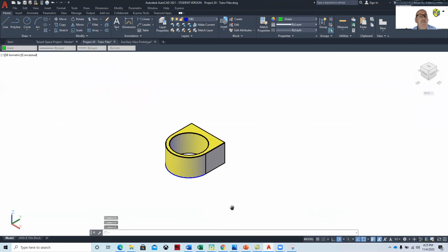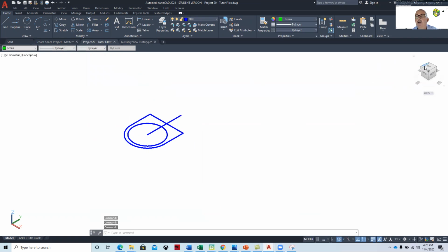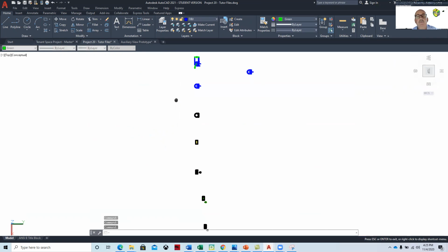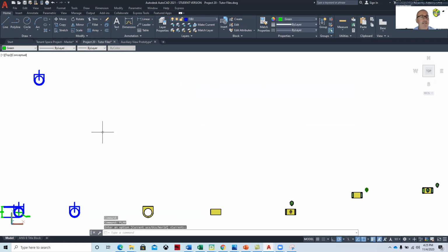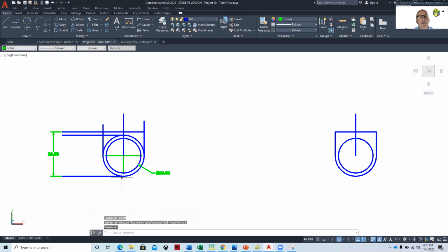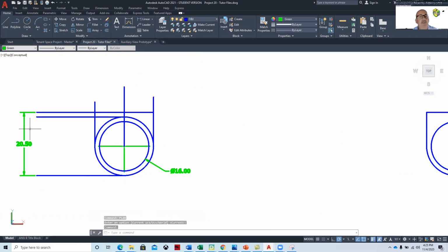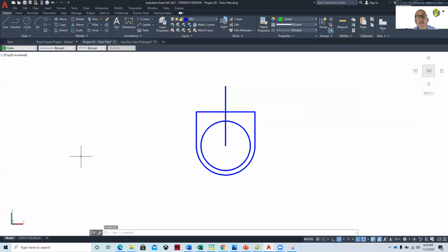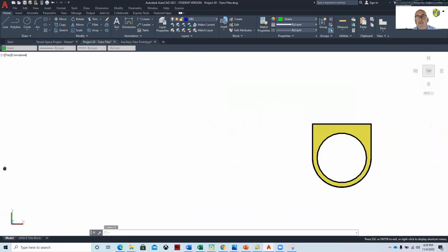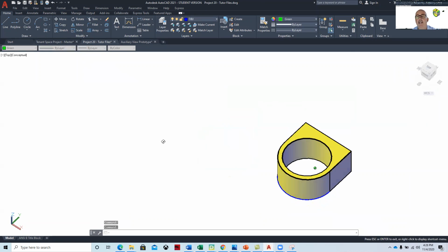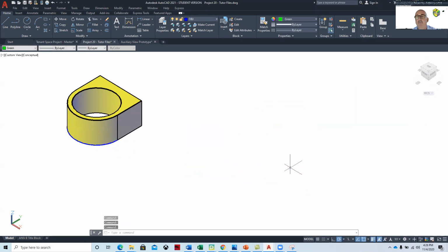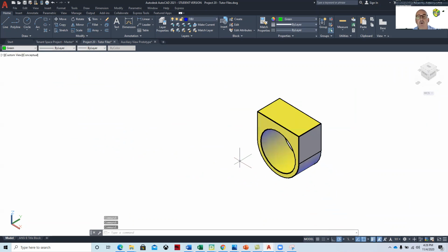If you look at how it's made, we start off in the top view. Let me type in plan because it twisted on me. That way my x-axis is correct. This is the basic shape, and this is how we started to model this based on the geometry. We model it flat. I would probably make this 19 millimeters, and I'd have to increase the outside respectively so that it would fit on my hand. Then we trim. Once we have that trimmed, we'll press pull it into a shape. And then we'll 3D rotate it.